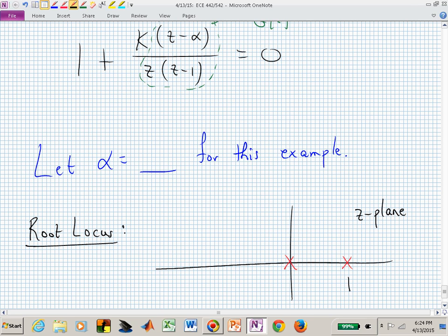And then it gives us a pretty benign root locus, doesn't it? What's our root locus do if I cancel that pole at the origin? It's the entire left hand. That's what we had before, except now we're starting at z equal 1 and going to minus infinity. That's too easy, so let's do something else. But you could do that. Is it clear that you can cancel that pole? And that would be a very straightforward, simple controller and a controller to design.